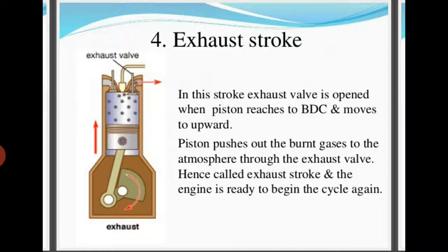The piston moves from BDC position to TDC position, that is, from bottom dead center to top dead center, and pushes the burnt gases out from the engine cylinder. The exhaust stroke is completed as the piston reaches the TDC position, and the engine is ready to begin the next cycle again. That means the working cycle again starts from the suction stroke.